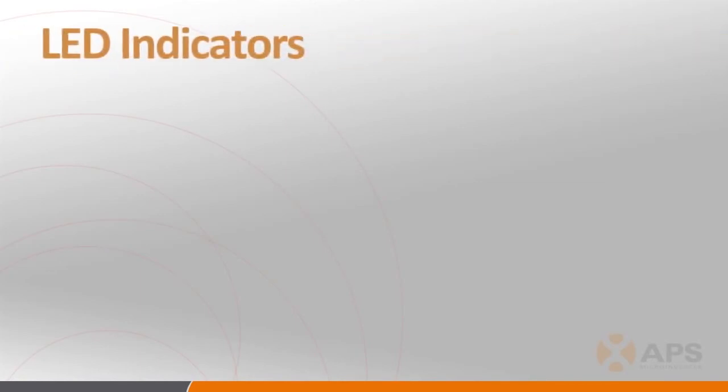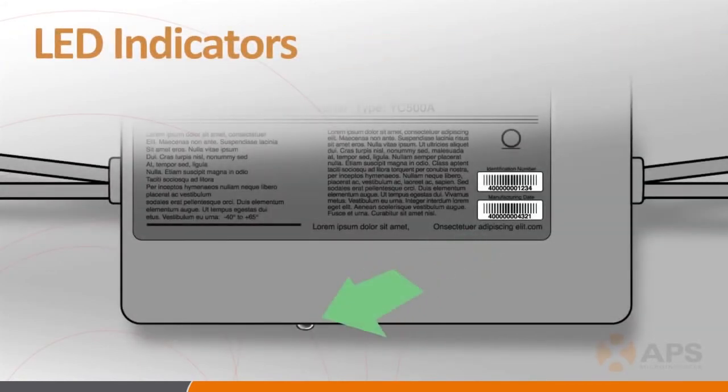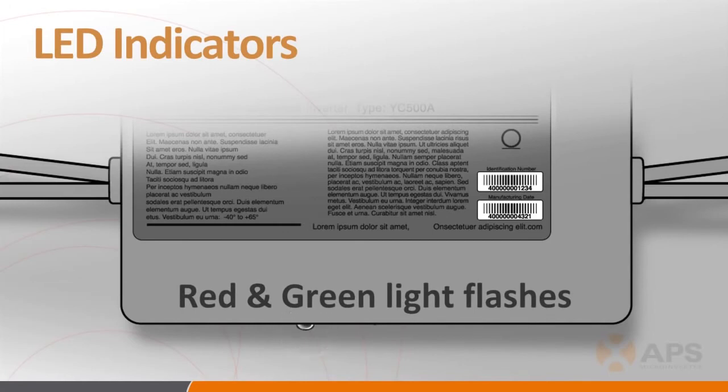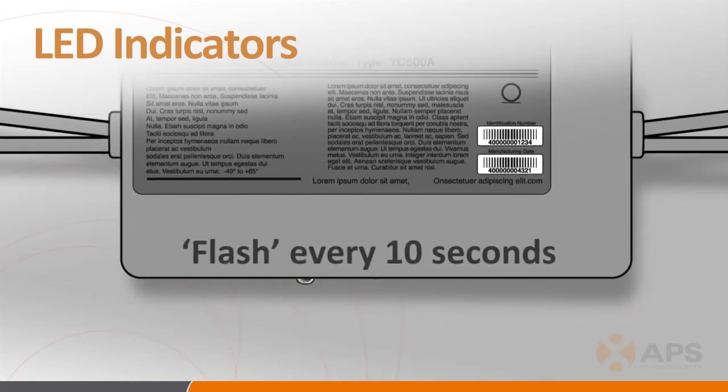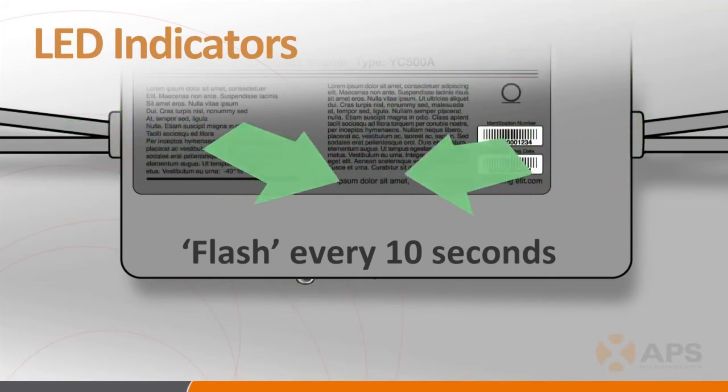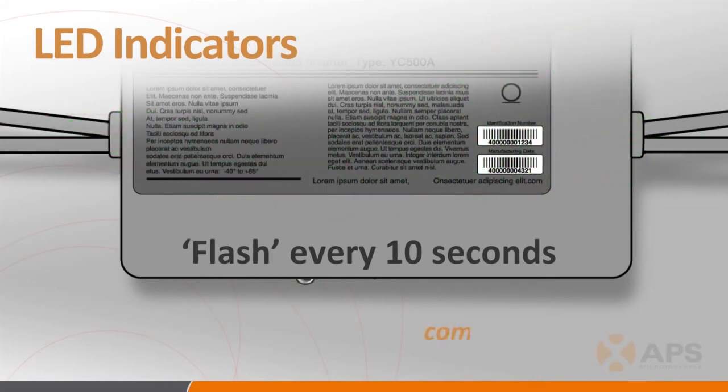Now that the system is energized, a few words about the inverter LED indicator lights. The inverters have a number of LED indicators that are extremely useful in determining system status beyond system startup. Assuming all is good with the system once it has been energized, the LED will flash green slowly, every 10 seconds, meaning the inverter is producing power and communicating with the ECU as expected.